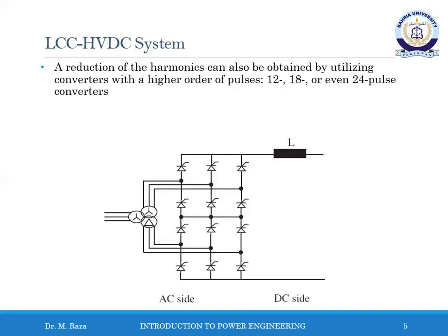The transformer of a 12 pulse bridge has a YY delta 3 winding configuration, such as shown over here, or a combination of YY and Y delta transformers formed with single phase transformers. The transformer here can be either a 3-phase transformer or a single phase transformer. The leakage reactance of the transformer is typically between 10 to 18% in order to limit the current during a short circuit fault of the bridge arm. The bridge arm is considered the single legs.